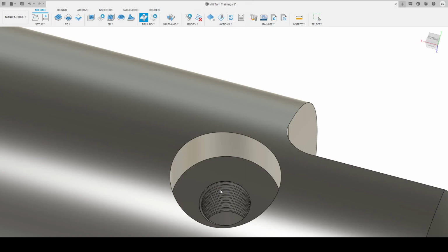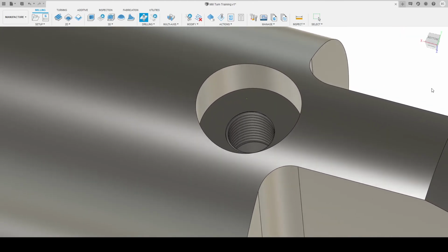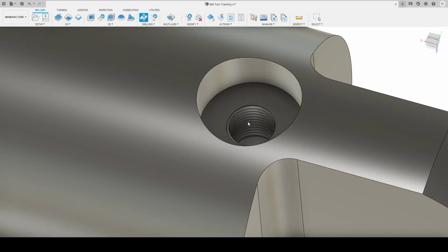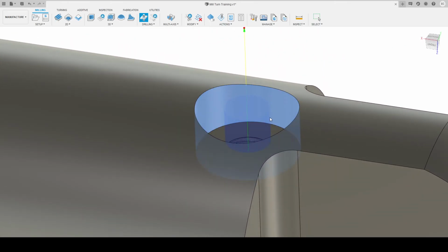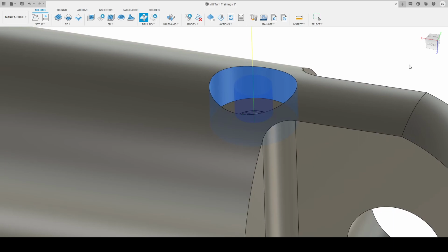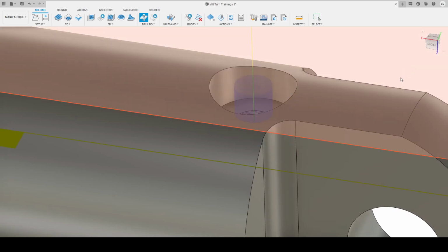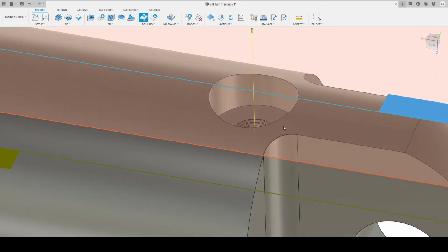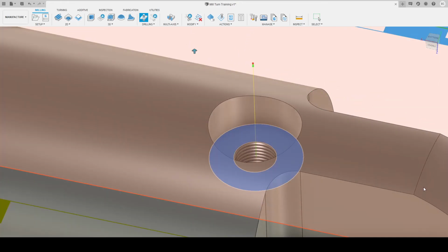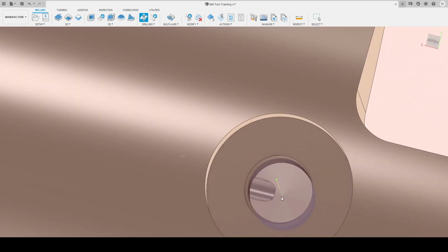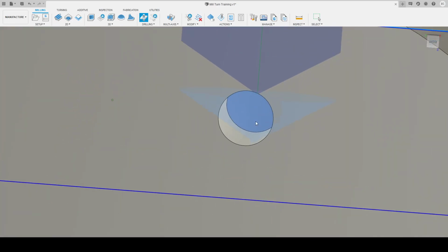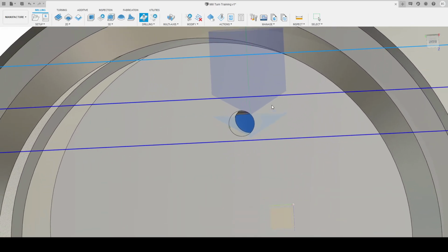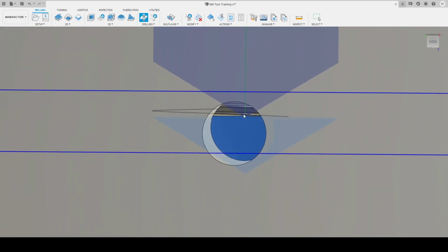And then the faces that we want to drill is not going to work. Because we can't actually select a face, well, we can select that one, I guess. So let's select that one. So now it knows that we only want to drill this bit, which is fine. So we'll change our heights. Hopefully this is making sense. To the top height, we'll go selection, so we want to drill from there, and then the bottom height we want to drill down to there. So now you can see that it's not correct because our drill is only drilling to here, so the tip is drilling to here.